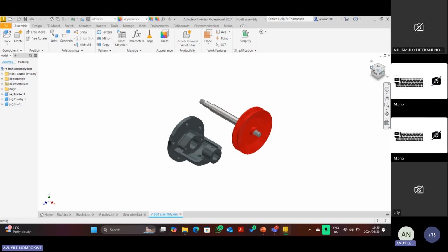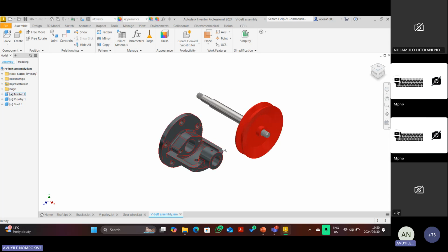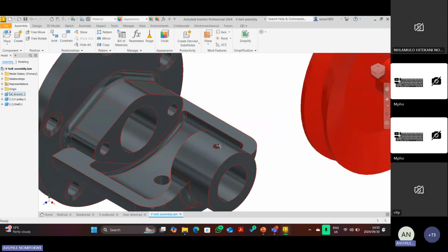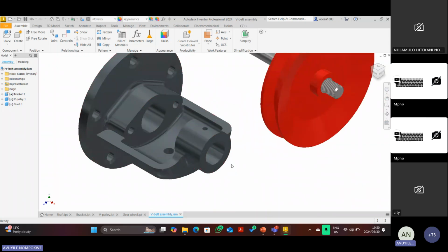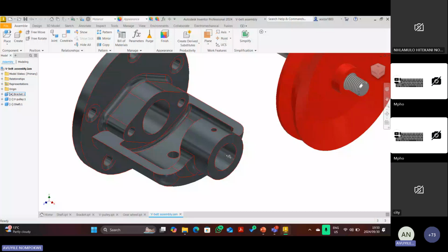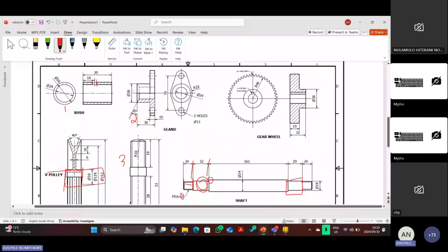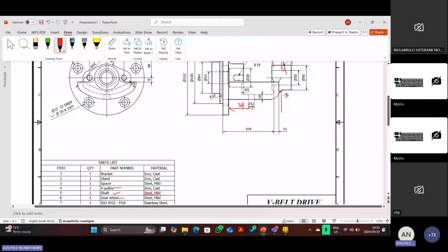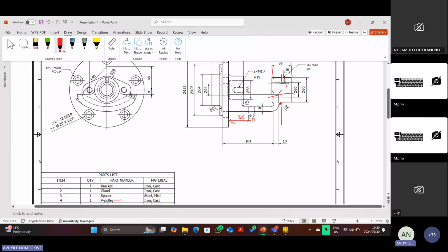So now, what I will place now, guys, it's the bush, right? I didn't draw it for you, but I have it, the bush that comes in here. Because the bush, it's diameter 30, and even this, it's diameter 30. So the bush goes in there, and even the length of our bush is 39, so I mean that it fits here, right?